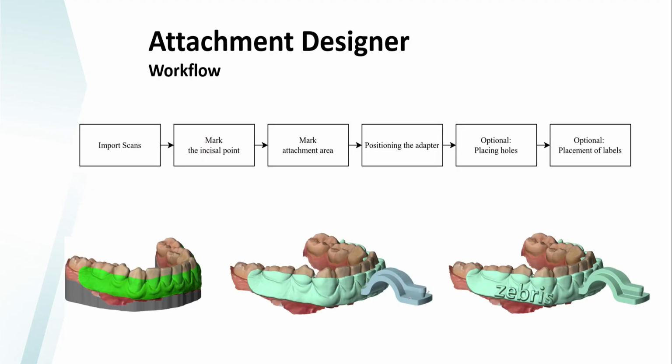The attachment designer workflow is quite simple. At first we import the scans, we mark the incisal point on the scan, we mark the attachment area and position the adapter. As optional steps we have the placing of holes and the placing of labels.